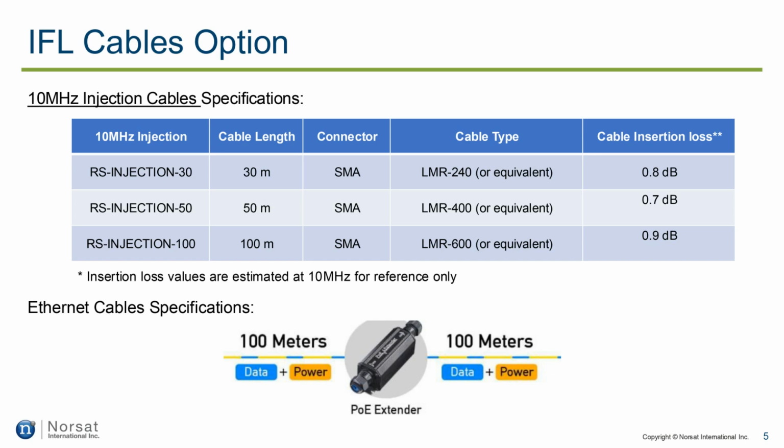Thus, the distance between the antenna and the system is a concern. Beyond this limit, signals will become indiscernible and distorted. There are two main reasons for signal degradation over Ethernet: wire resistance and interference. Thus, a PoE extender is very important to achieve long-range Ethernet deployments, which have a 100-meter limitation due to signal attenuation as data travels along the cables, resulting in signal degradation and potential data loss.